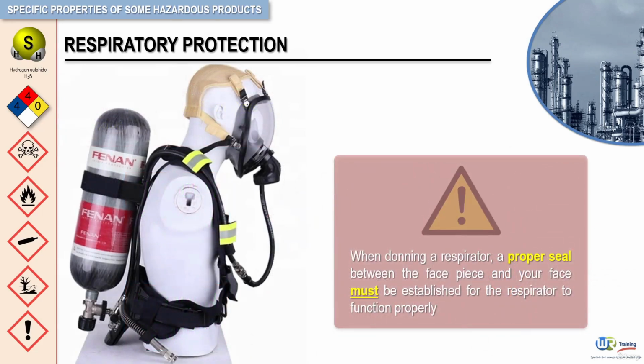When donning a respirator, a proper seal between the facepiece and your face must be established for the respirator to function properly. A user seal check must be performed each time you put on a respirator to ensure a good seal has been established.